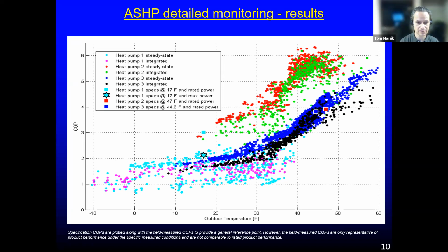I should also point out that the efficiency of heat pumps is improving. This is again a study from 2014, 2015. Now the newer models on the market, some of them have a better efficiency. With some of them we see that they stay above a COP of about 2 above about 0 degrees Fahrenheit. I should also point out that I mentioned 2.5 as the threshold for rural Alaska, but different communities are different. I saw in the poll at the beginning that we do have a lot of people in Fairbanks here. So in Fairbanks, for example, the magic number is a COP of about 2.